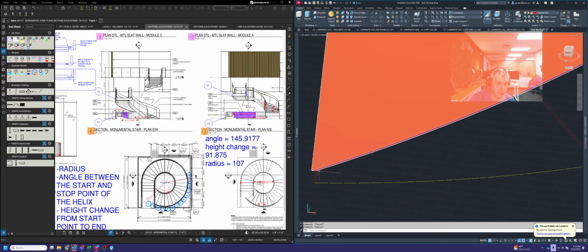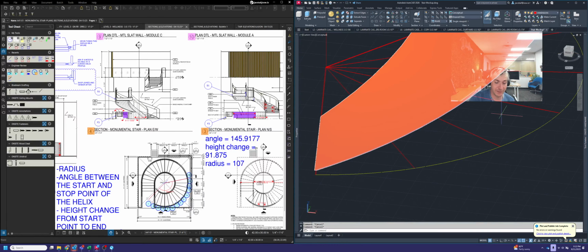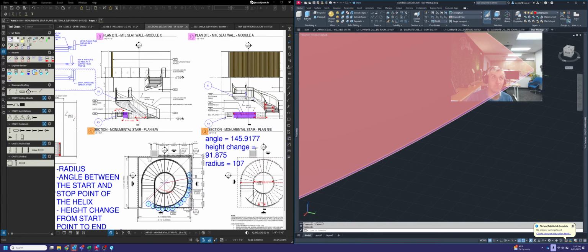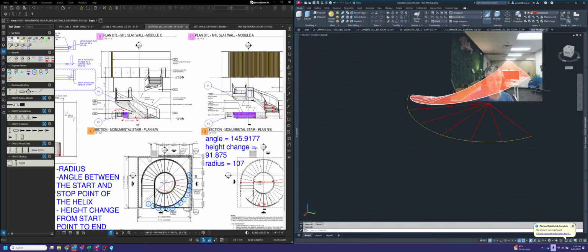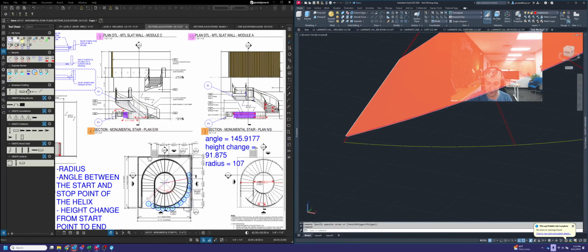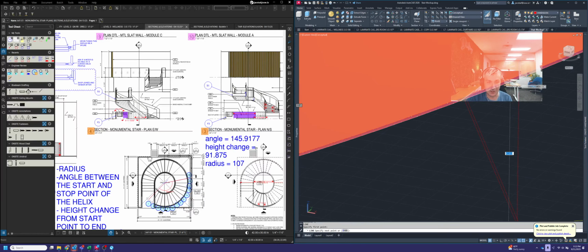I almost feel like what I would do is maybe take a helix from that point to here, which, yeah, I think that's how I would probably do it to get it to be perpendicular to the panel versus the floor. You could probably also do one of these extract edges numbers, like up here, which should give you that helix again, unless it turns it into a spline, which it looks like it did, unfortunately. Dang it. I was thinking maybe that would be an easy solution to that.